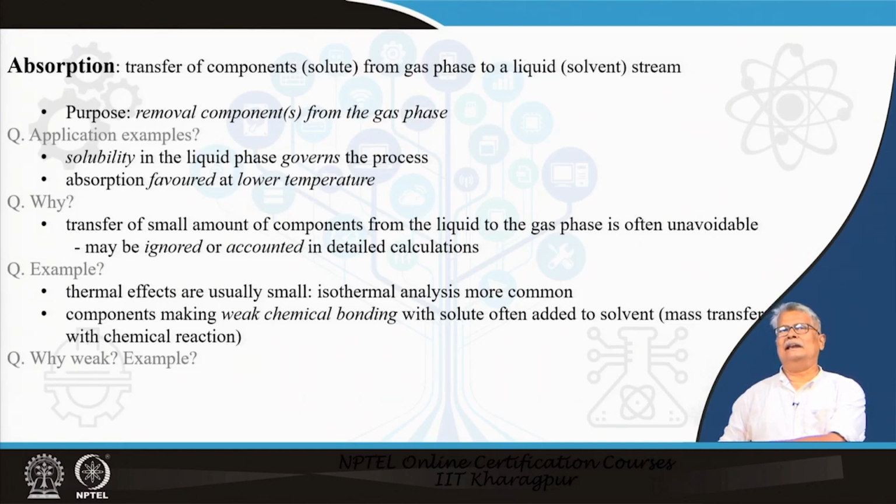Now, the entire process is governed by the solubility of the component in the liquid phase. Normally, such phase transfer from one phase to the other is associated with liberation of heat. So, quite naturally from basic thermodynamics we can guess that absorption is favored at lower temperature.